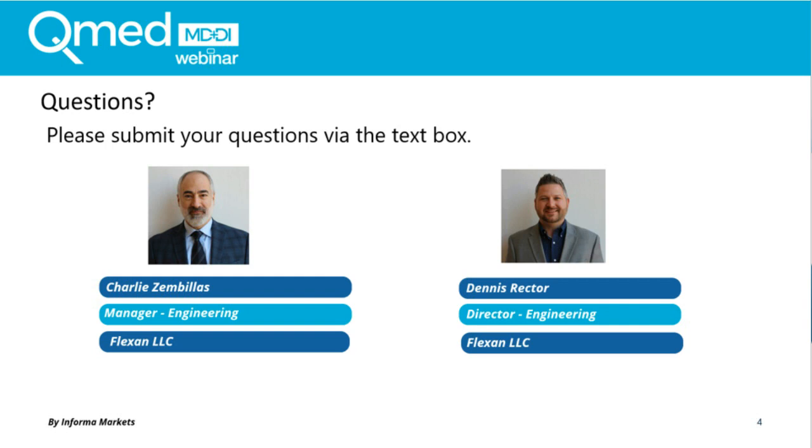In conjunction with the laser mic that monitors the OD 100%, we also do startup dimensions by the extrusion operator as well as our QC dimensional group, and we monitor the process every 30 minutes for all CTQ dimensions. And with what Dennis mentioned, generally the operator will take a section. You can measure OD, ID, wall, any CTQs as he pointed out, meaning critical to quality. All right, thank you, gentlemen.